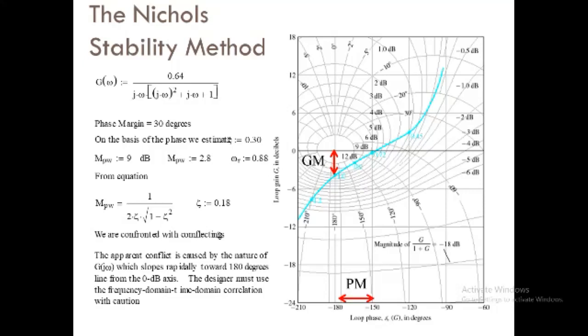Then the next one will be 0.1 into 10, that is equal to 1 rad per second. Similarly, the next one will be 10 rad per second, and so on. That is 10 times the previous value, and it is called a decade apart. Hence, the first 2 for the above scale is 0.2 rad per second.